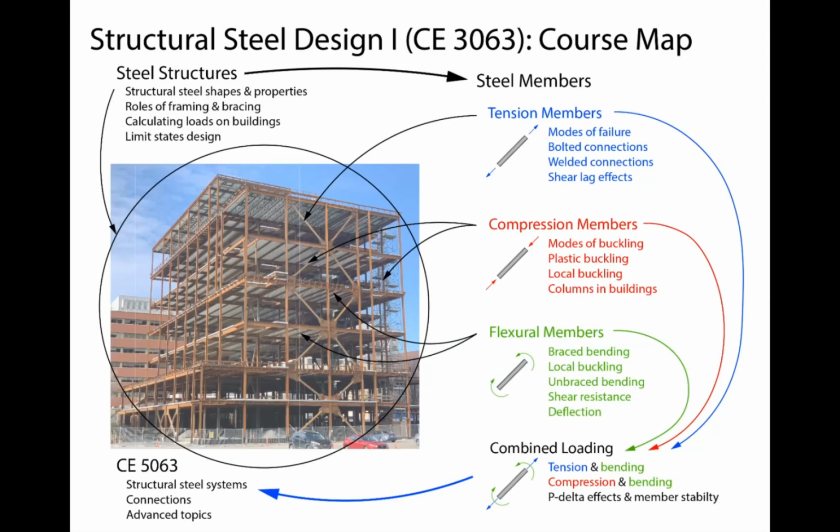Tension members, for the most part, tend to be the braces in your structure. You're going to be looking at tension-only bracing on assignment 2, not the design of the members, but the calculation of the tension forces acting in those elements. We talked a little bit about what tension-only bracing was in lecture 4, but you could have tension-compression bracing as well, so you might have to design braces for tension or compression. Members that are primarily tension members tend to be tension-only bracing in structures, and we'll see an example of what that looks like today.